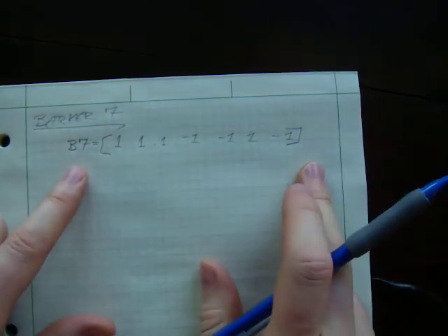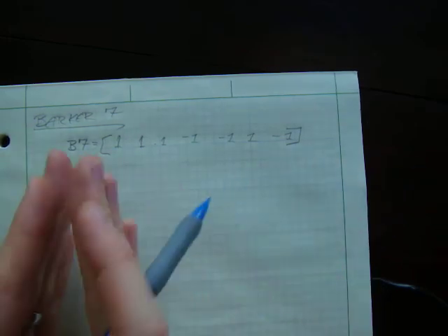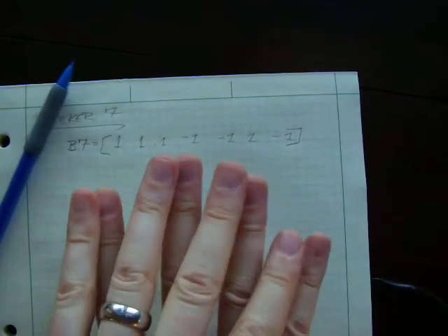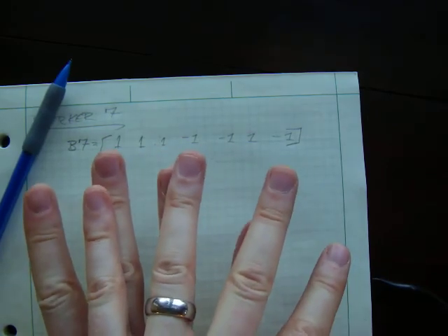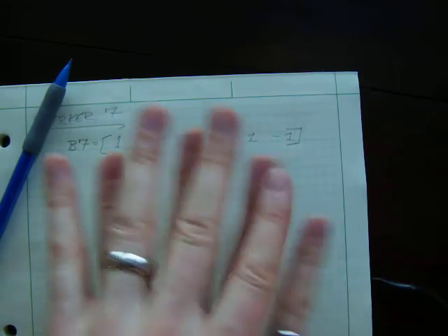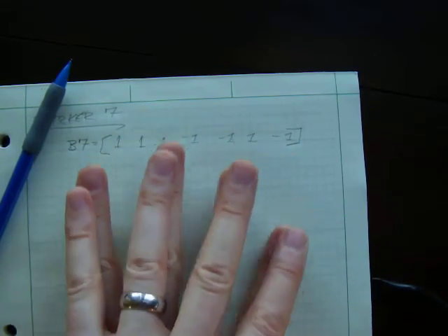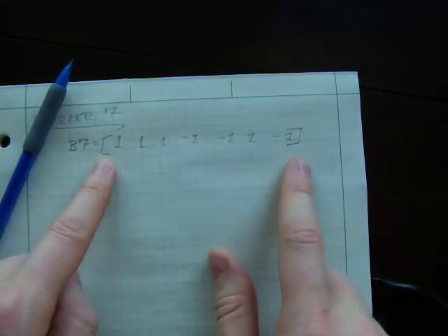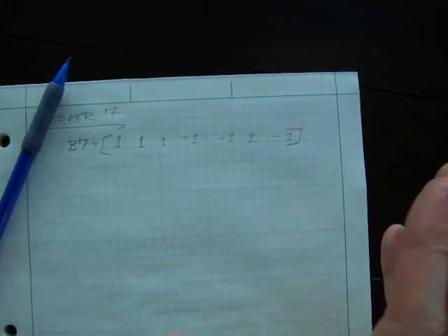This is the sequence that's transmitted. If it's transmitted in this order and you shift it to either side and try to correlate again, they don't correlate unless they're right on top of each other. The longer the Barker code, the better it gets, and the more it suppresses the side lobes.